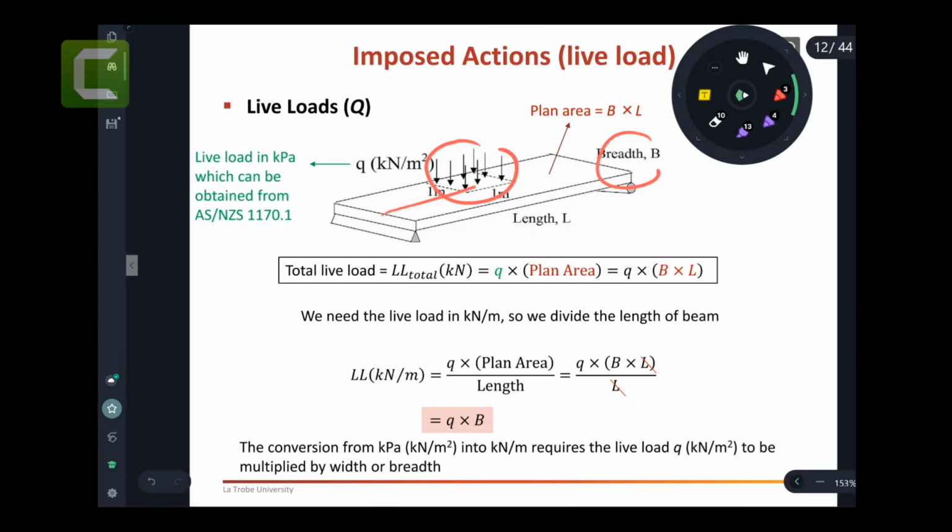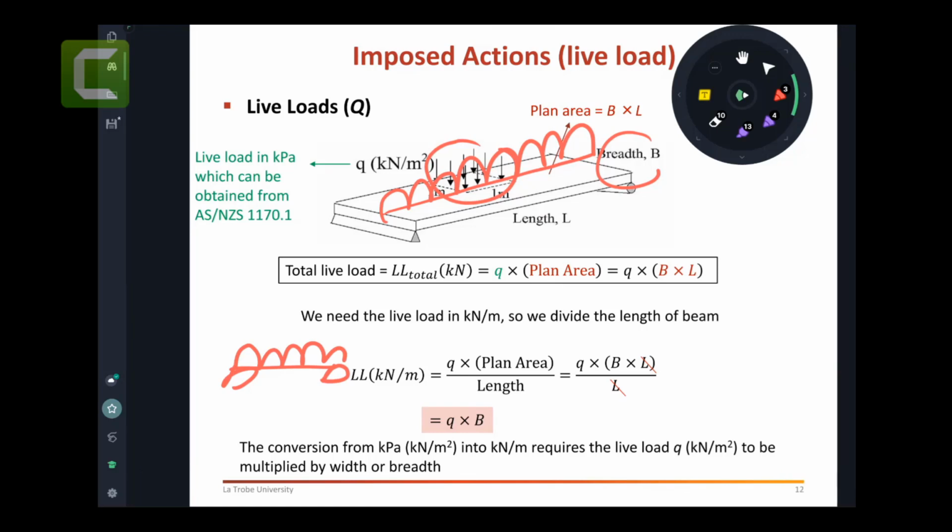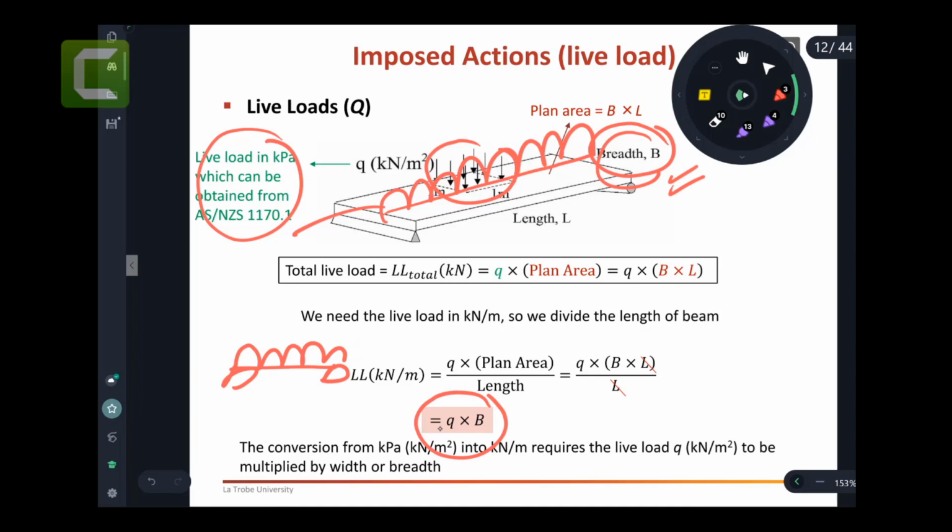And then I need to convert it to a line load that represents the whole story, and then I can do whatever I have to do in terms of what you studied in Structures 1 or Mechanics of Solids. How to do this? Simply, we multiply the pressure by this width. Multiply the pressure by the width. Now, that will give us this profile.